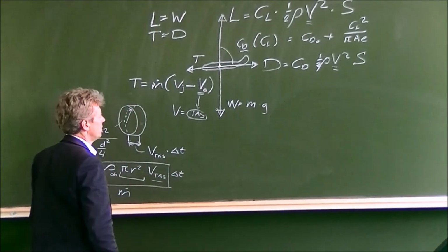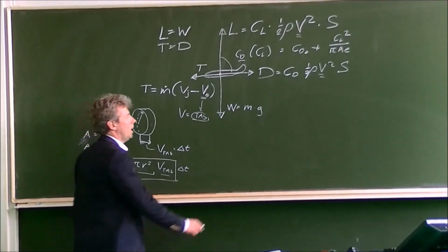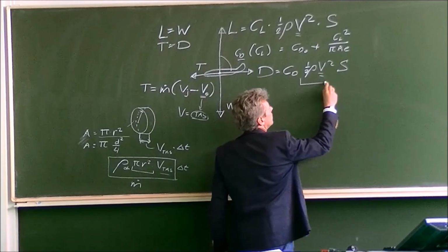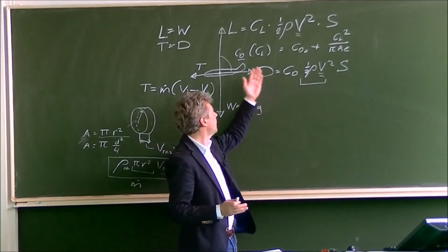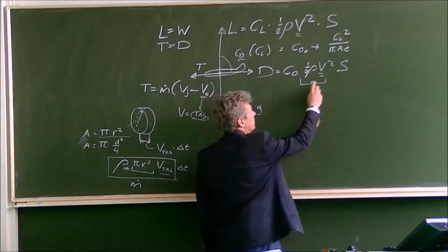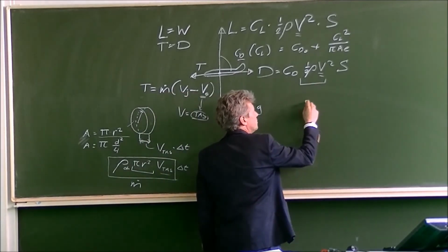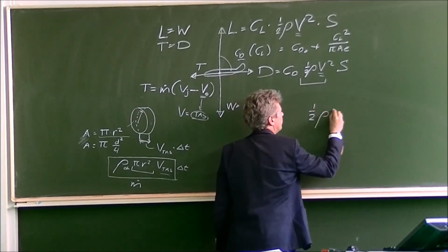Then there was also a question about equivalent airspeed and true airspeed. I mentioned the dynamic pressure here. The dynamic pressure is what the aircraft feels with its drag and the lift, but also with the instruments. And the speed scale is based on that using this equation, half rho v squared.